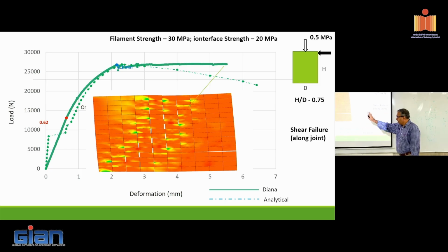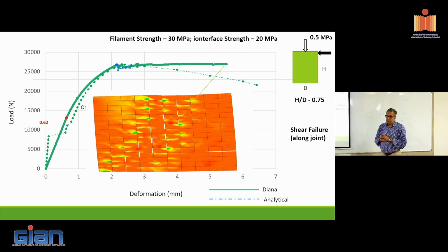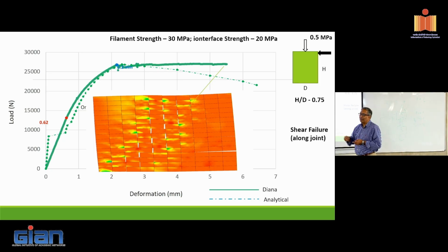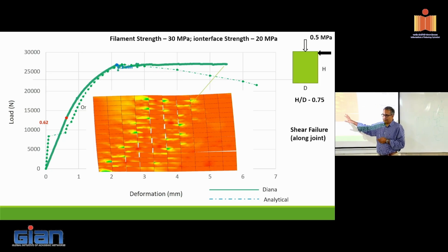Remember, this is from an analysis of what we call a masonry pier. What's a masonry pier? It's a wall made of masonry, which has some compression on top. So you see the compression on top, right? Which is subjected to the horizontal force. That means that this particular wall is designed to carry horizontal forces. Where would I see a horizontal force? When you have earthquake or wind, right? Wind would be more out of plane, and when you're talking about seismic, the significant resistance comes from the in-plane direction.